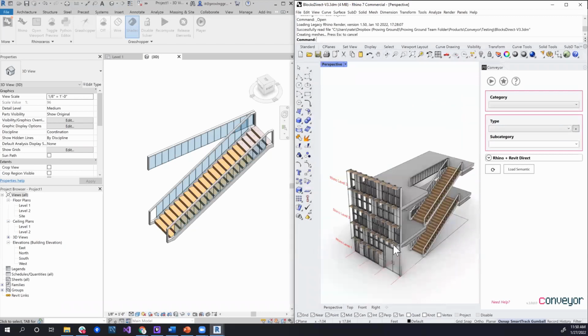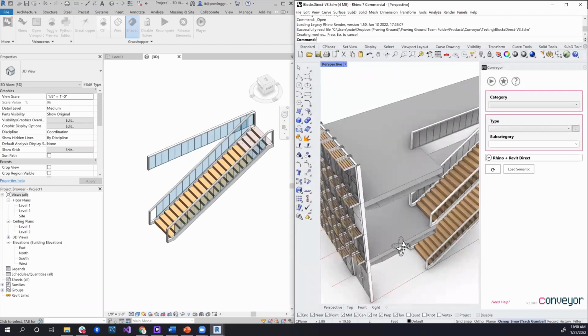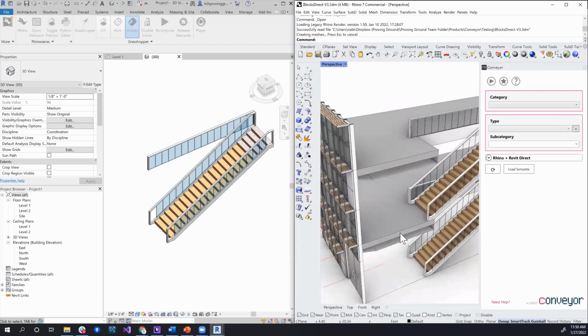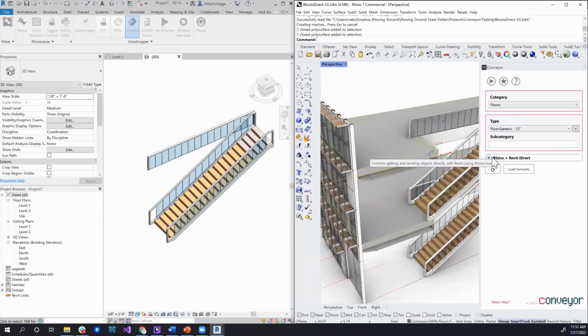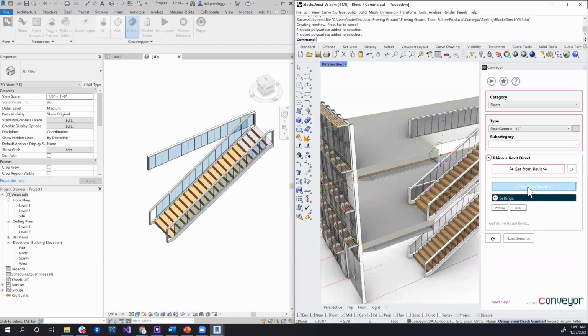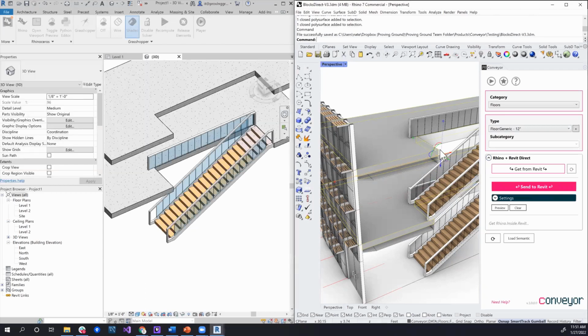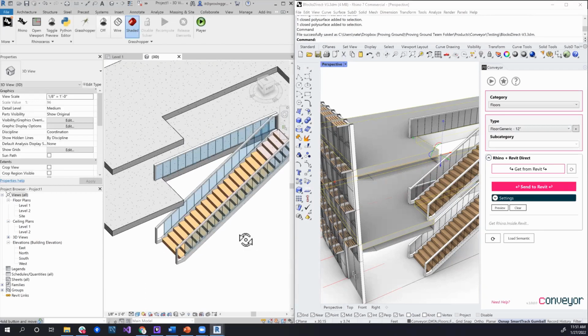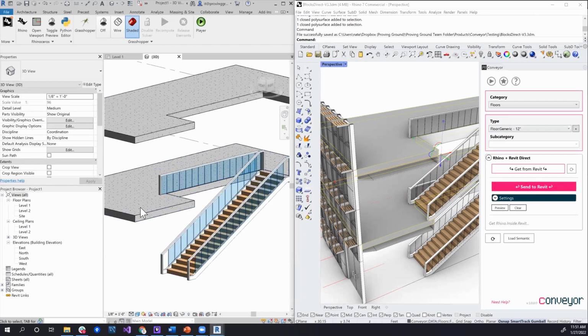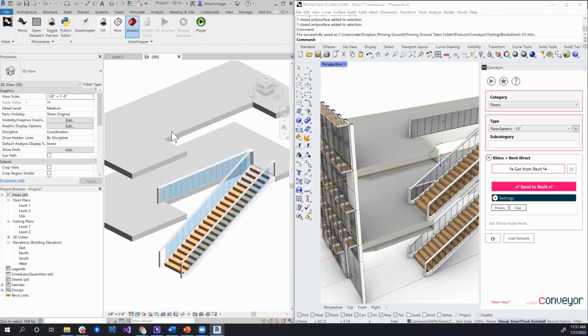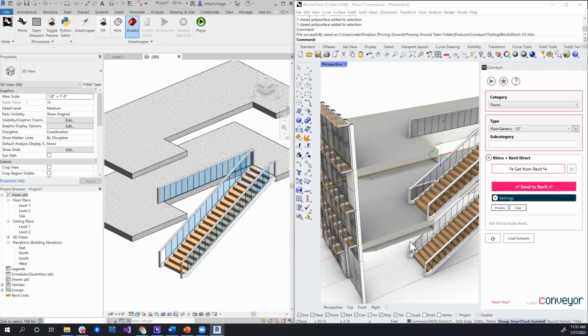So there are the direct modeled Rhino objects that have been saved in this file. I had it open as a separate application before. It's now open through Rhino Inside. And what I can do here is select a couple of these objects. Then there is a Rhino-Revit Direct toolbar, and now that I'm opened up in Rhino Inside, I can say, let's send these 2 floors over to Revit. It's going to open up a connection and send them right into the model. So now we have those 2 floors with, again, materials assigned to them applied.